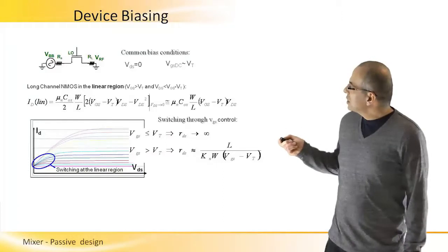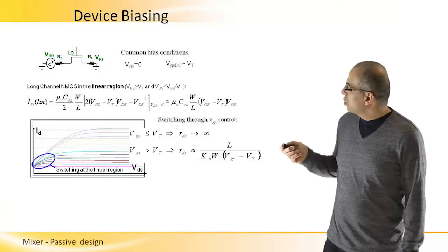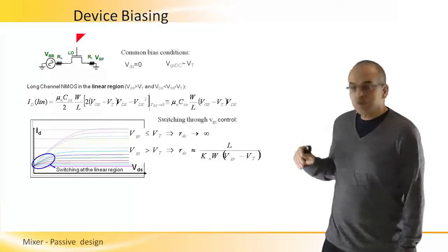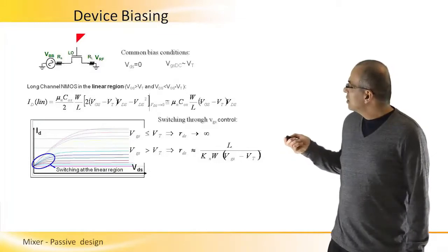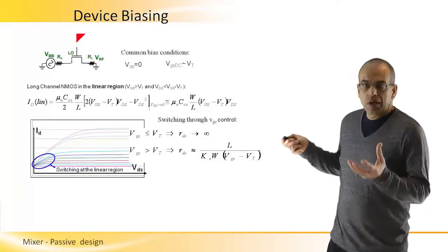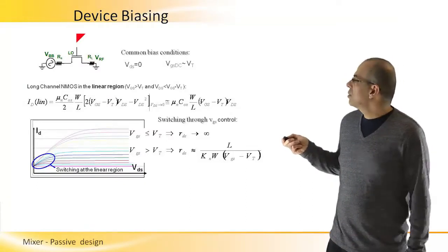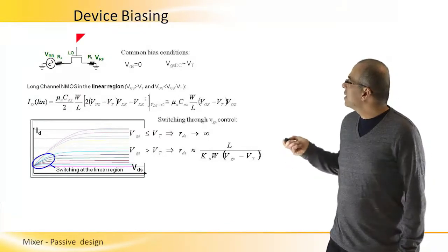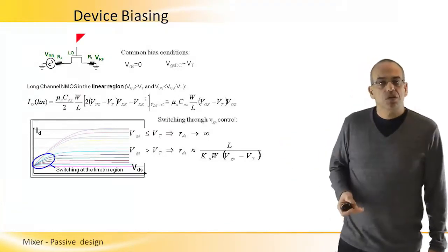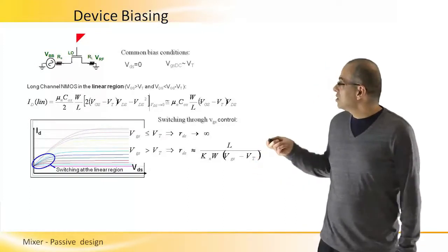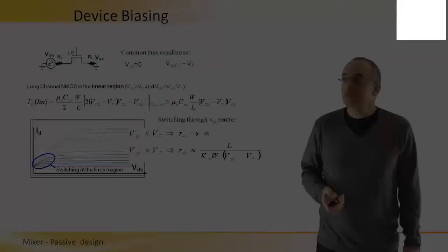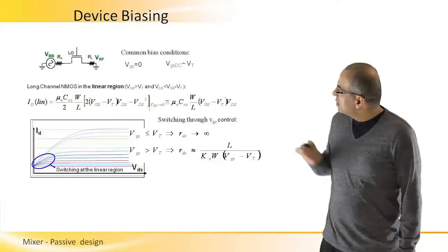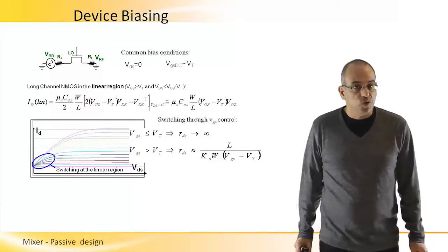So when we add the square wave LO signal, we have either higher or lower than VT voltage between gate-source or gate-drain, and this opens or closes the NMOS used as a switch as fast as we can. So really, gate biasing is very close to VT to achieve this performance.